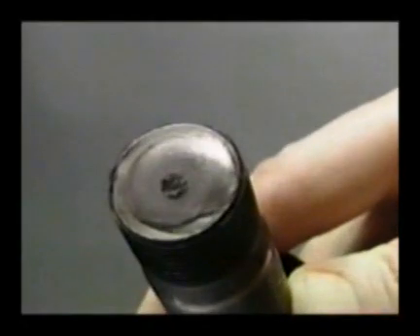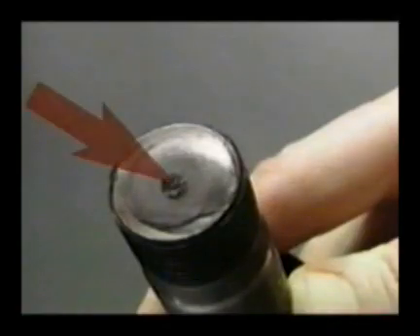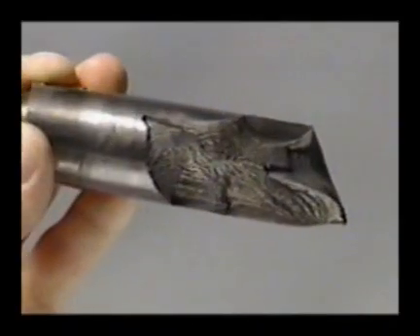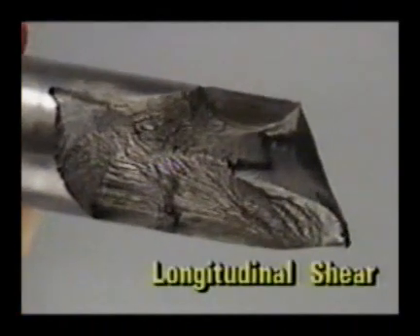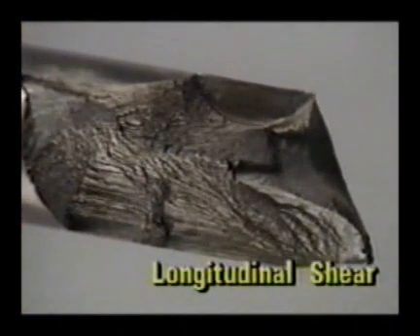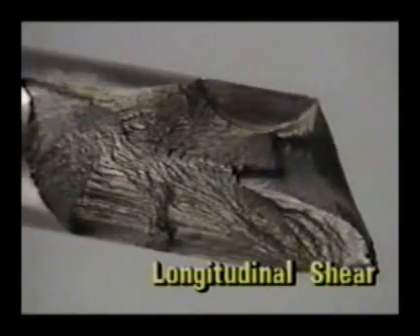Much of the fracture face is smooth and silky. At the final fracture, the surface is rough and dark gray. Final fracture often occurs near the center of the part. If fracture occurs along the part's length, it is called longitudinal shear. Grain flow can be exposed, producing a woody gray surface. How many surface features can you identify that characterize this as a ductile fracture?